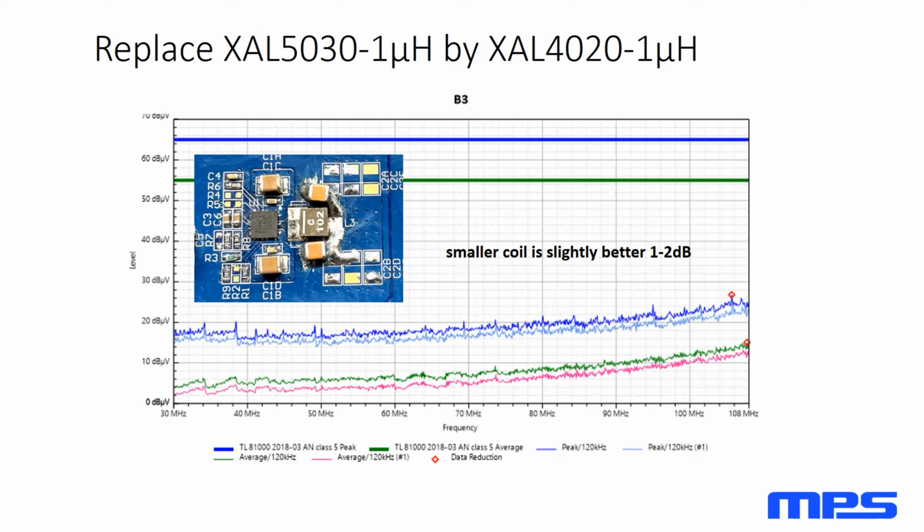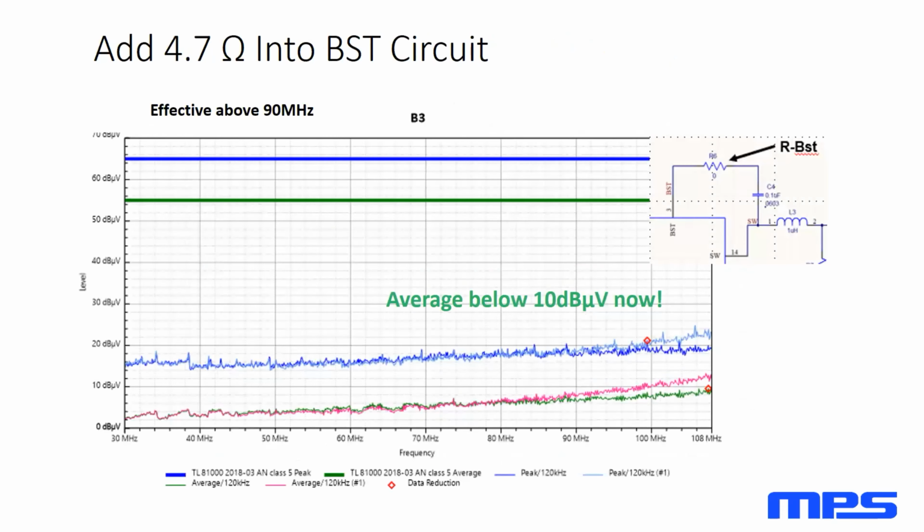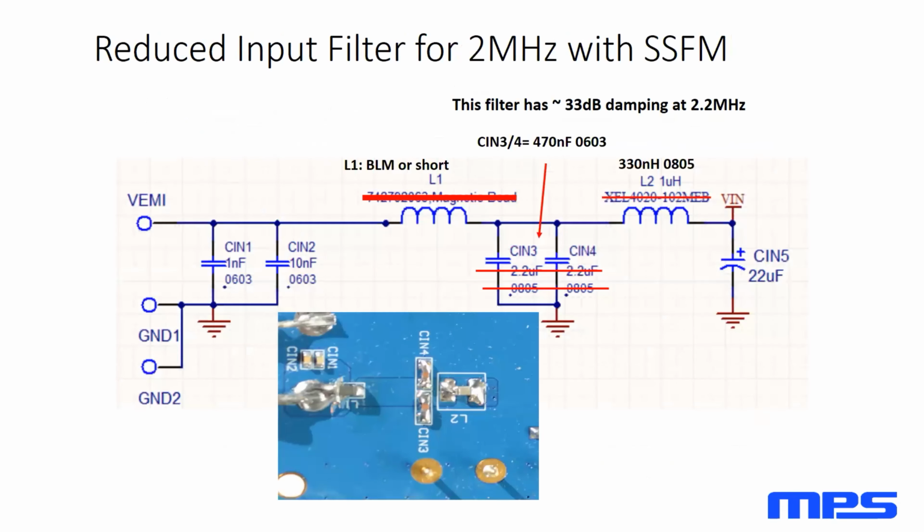Okay. And then again, looks like more of a comment, but if you want to comment on their comment regarding cap size choice: something really important to remember is that larger size caps show reduced DC bias effect, loss of capacitance as a function of applied voltage. Yeah, that is absolutely a key design criterion when you're looking at this stuff.